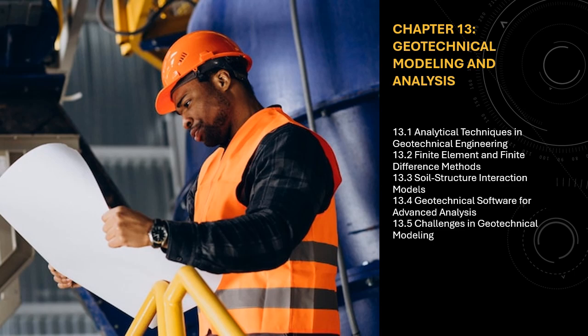13.1.4.2 Nonlinear SSI models. Nonlinear SSI models consider the complex and nonlinear behavior of both soil and structures under extreme loading conditions. These models are critical for analyzing the performance of foundations during seismic events or large static loads.